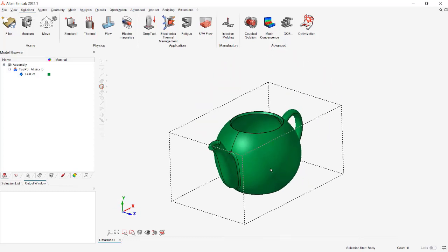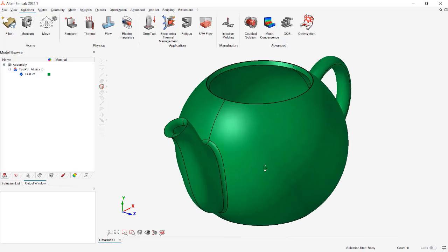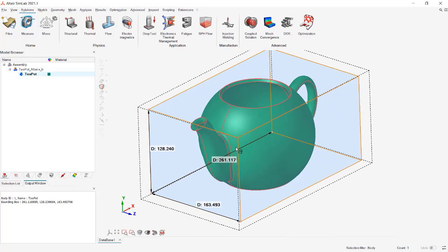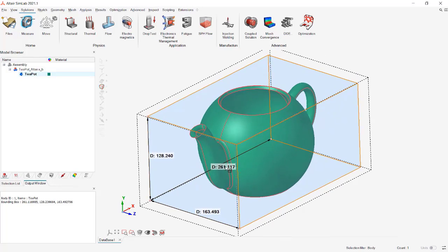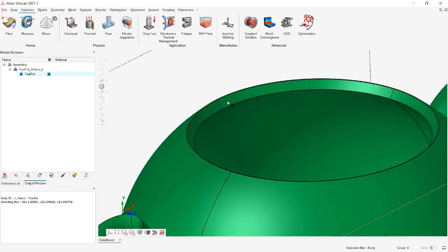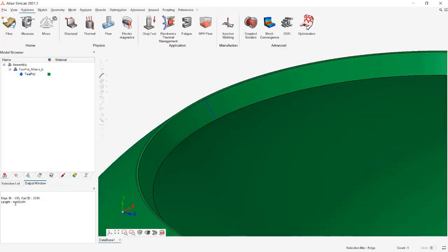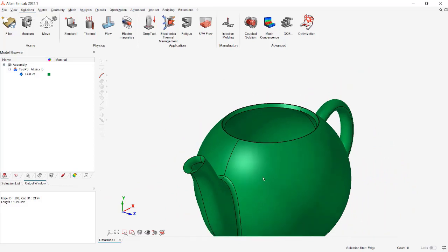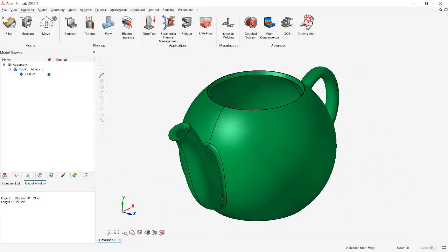All right. The first thing that I will do for meshing purposes is measuring this. I'm gonna get just the bounding box for me to have some reference in terms of mesh size that I should define. And then I will check on this length right here. Check the length. So this is 4.1. Okay. The unit I have it enabled, but I have imported this model as millimeter. So all you've seen, this value right here, will be in millimeter, but you could also enable the unit system to work with a visible one.